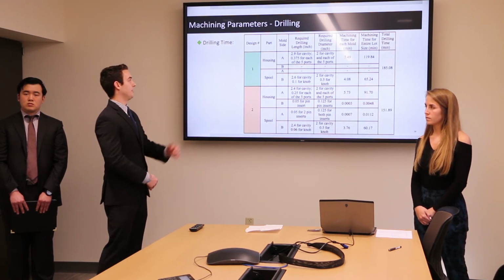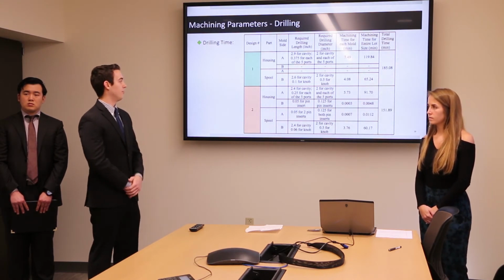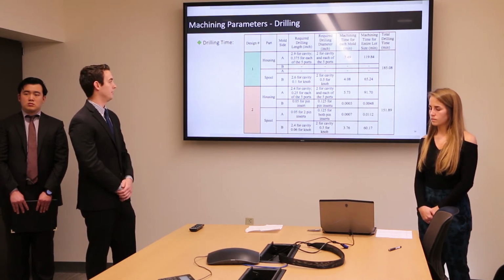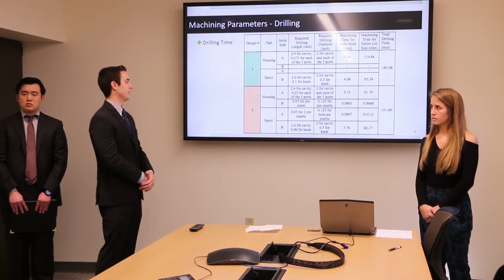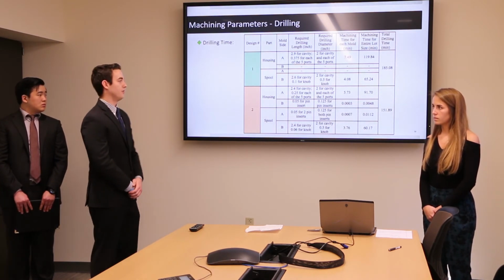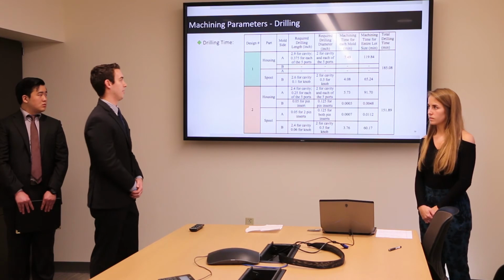And as you can see in our machining time for each mold, adding that 0.05 inch length really didn't add any time to our drilling time for our second design. So our total drilling time decreased from 185.08 minutes to 151.89 minutes from design 1 to design 2.